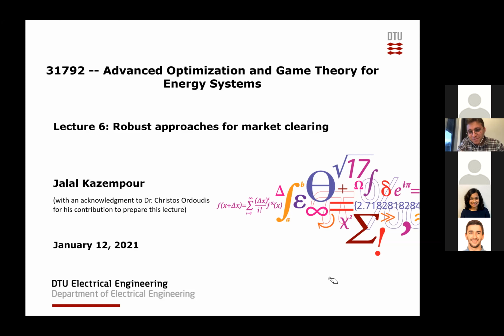So let's get back to our original example. If you remember, this is our real-time problem, just the real-time problem. We are minimizing the cost in real time, which consists of the production of generator 2, the adjusted production, and the load shedding cost, and also all our real-time stage constraints.